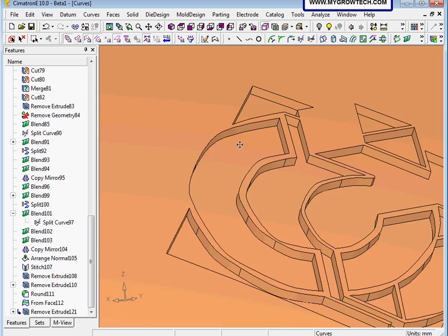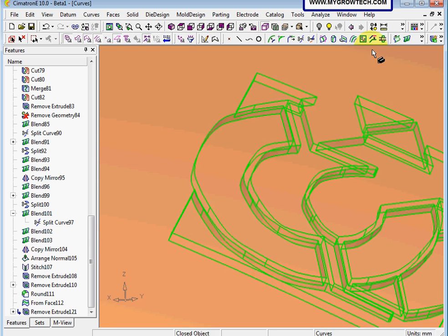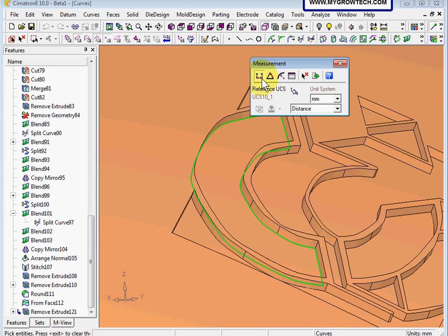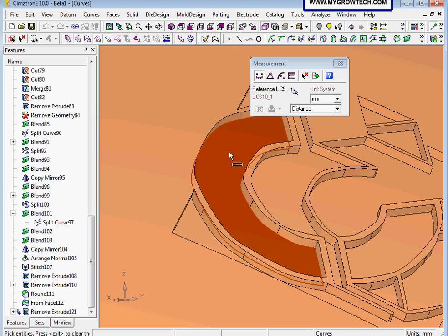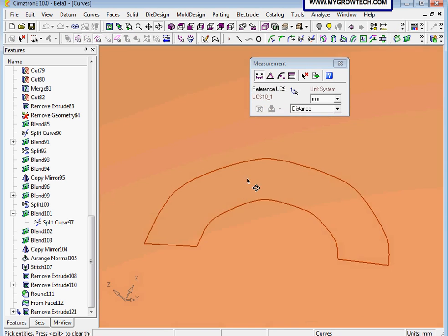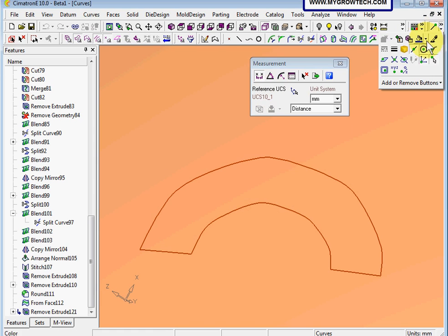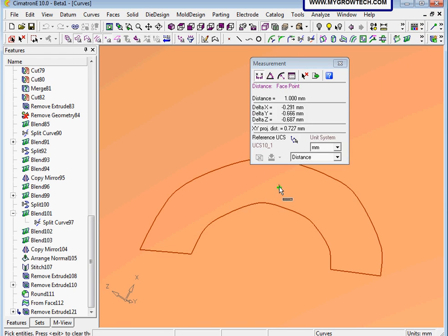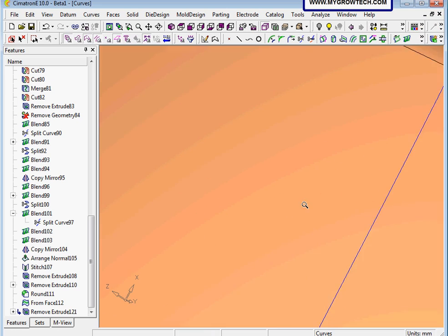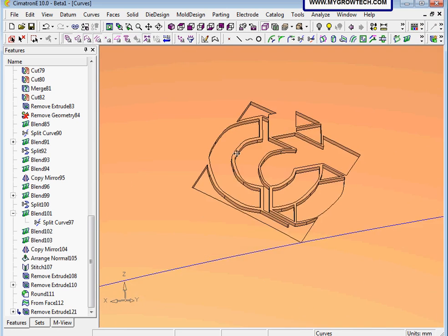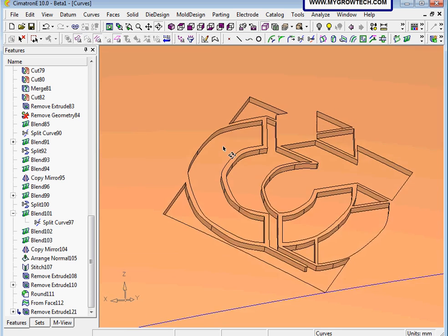So with the offset of -1, I still have a thickness from the bottom face to the back face of roughly 1 mm because I put -1. This is a new function, a new option for the offset.